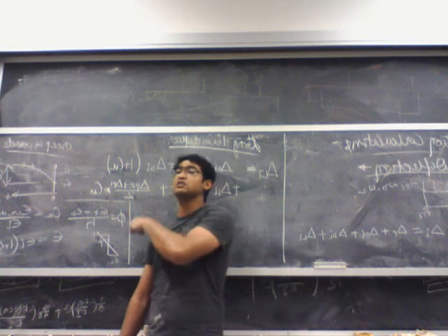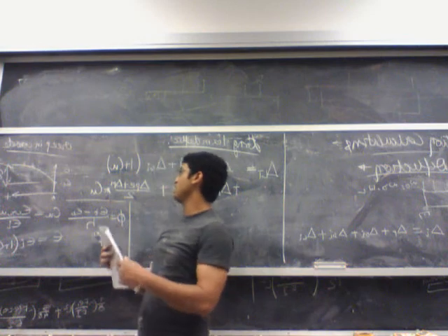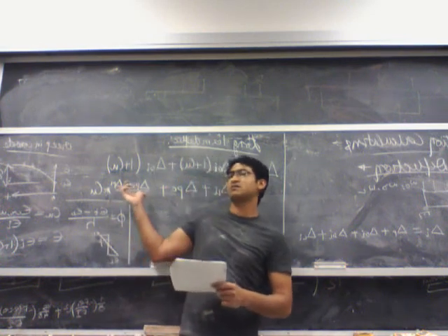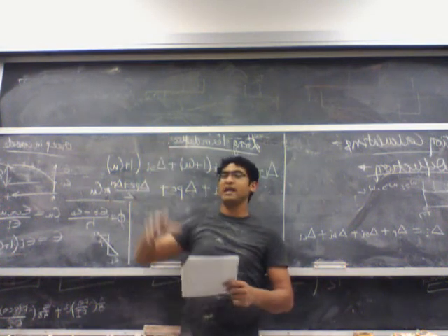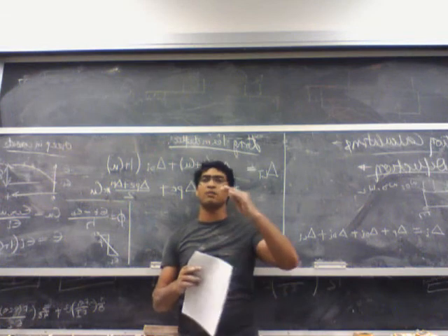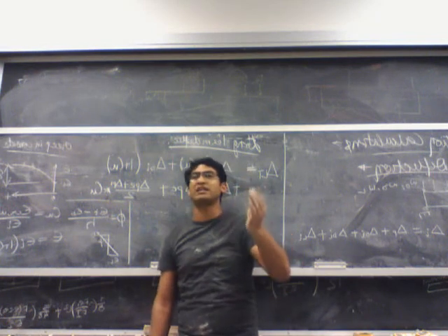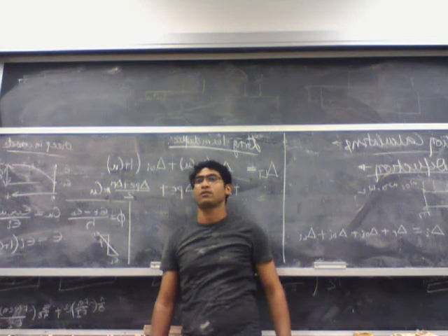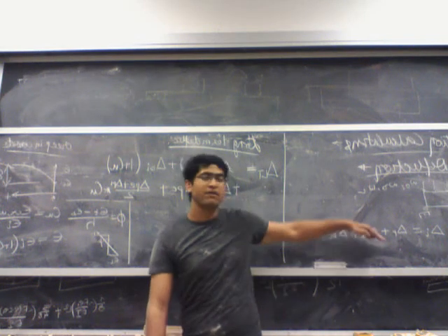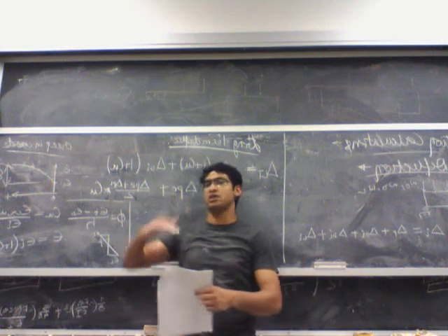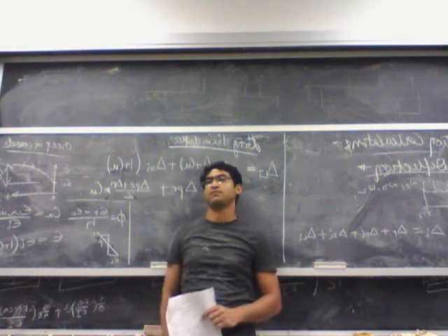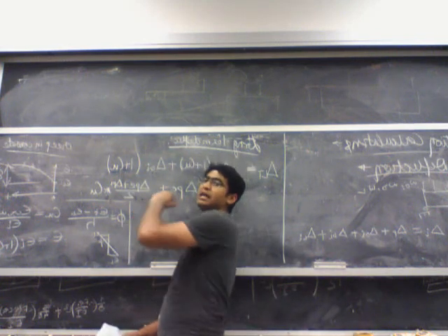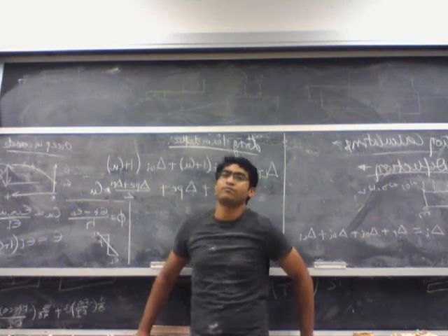So it is possible that if you have the correct amount of pre-stressing force and the loads, over the long term your beam might not deflect that much, or it might actually deflect upwards. So initially it might actually deflect downwards, but over time it might actually go up because of the creep effect. Yeah, because these two terms will be negative if your e naught is positive.